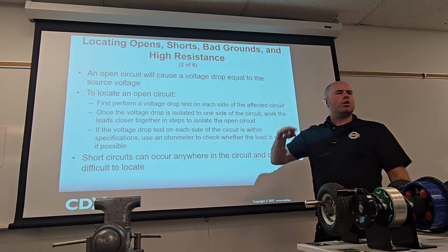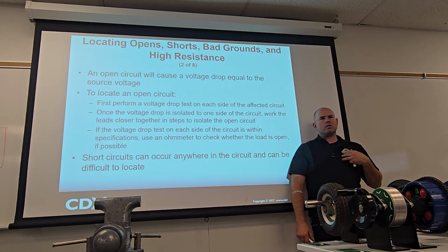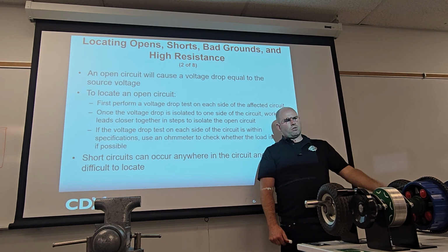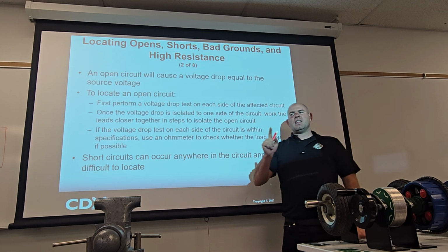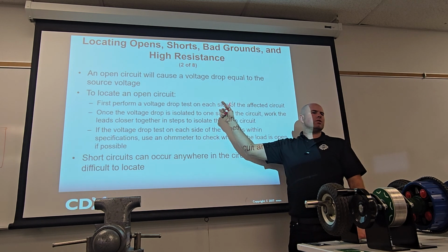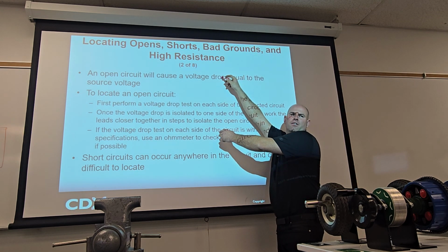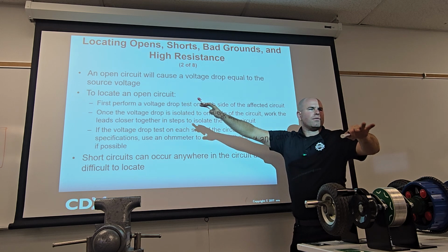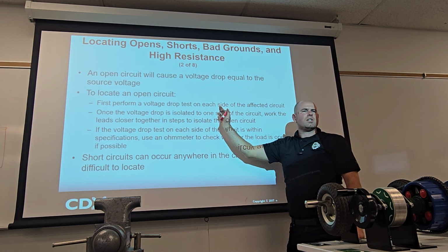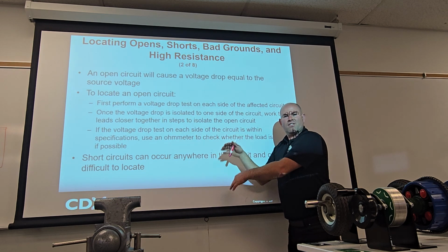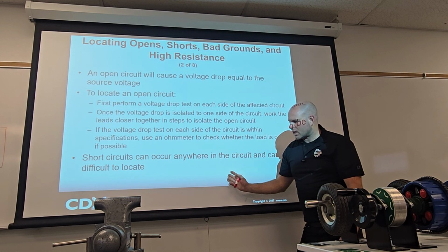So that way, you know what I don't want? And to be honest, as an instructor, but also someone who provides critical feedback to techs, I don't want to see your measurements and then have you write in your story that you're checking the fuse. If you showed me that you voltage dropped the positive and it dropped 0 volts, you're done. Don't check the fuse. Don't check any of that. It didn't drop any voltage. Ignore anything on the positive side and get down to the negative. And if the negative has the drop, then your remaining tests should all be in testing the negative.